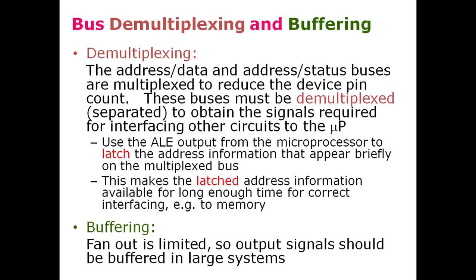While buffering is used to increase the signals, or to increase the number of devices to be connected with signals. Because the fan out of the microprocessor pins is limited, not many devices can be connected directly with them.